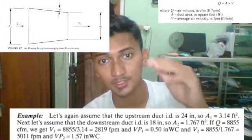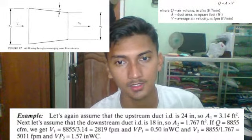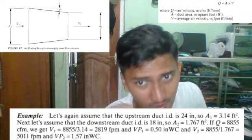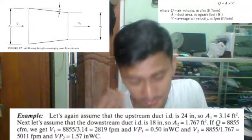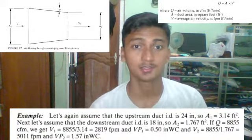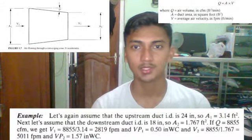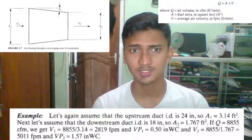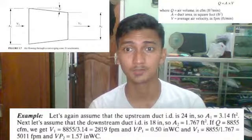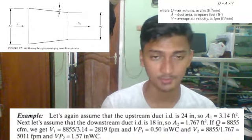While the velocity increases, the static pressure decreases, right? And this is easy to understand. But the relation always says that when the air velocity decreases, as in a diverging cone, which we talk about after this, the static pressure will increase. This increase is called static regain. This is more difficult to understand. It will be discussed in more detail in the section on the diverging cone after this slide.